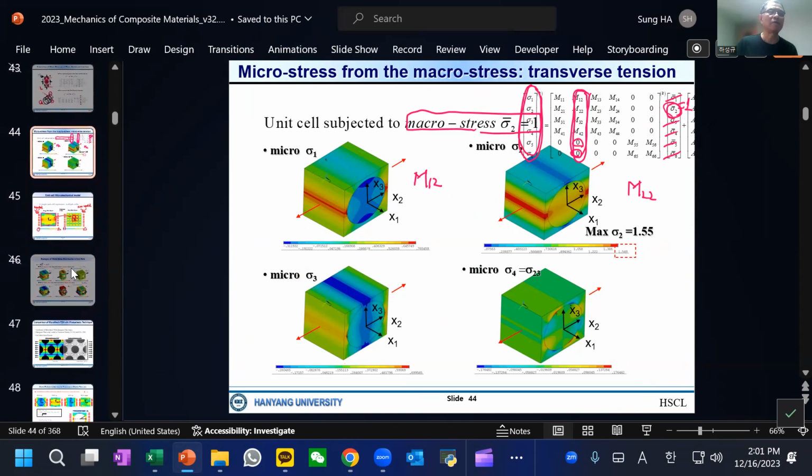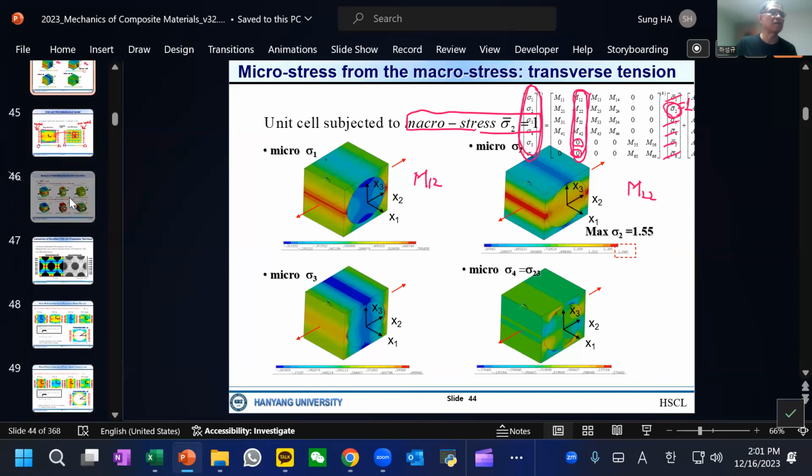But one thing I would like to show, for example, is the transverse load, sigma y. We often consider sigma y and sigma 1, etc. Now, sigma y will cause the stress distribution inside the resin and fiber. This color shows all the sigma 1, sigma 2, etc. As you can see, there can be a lot of different stresses.